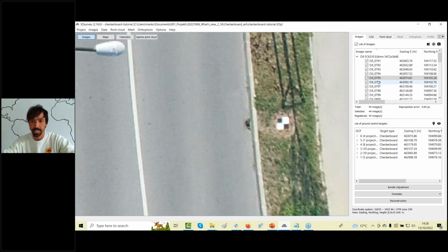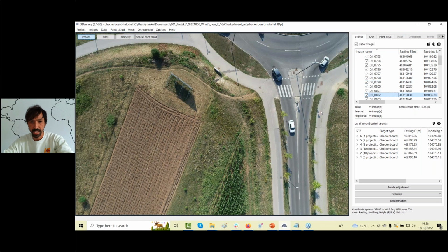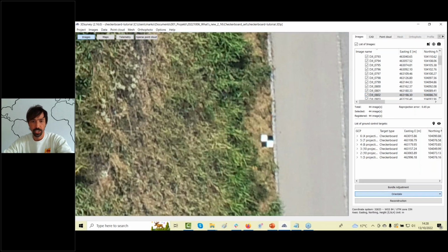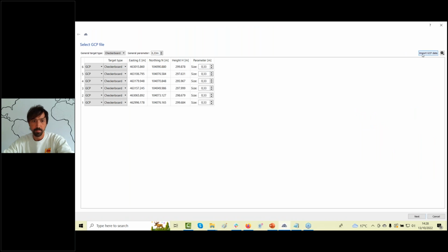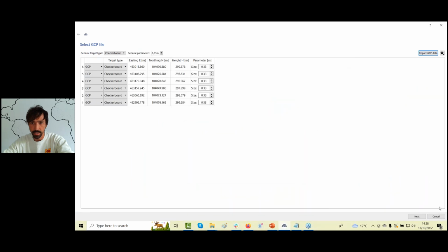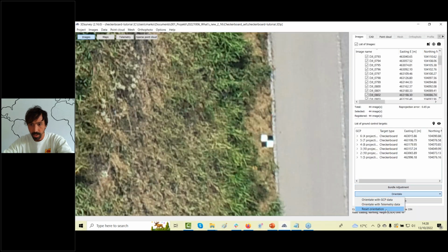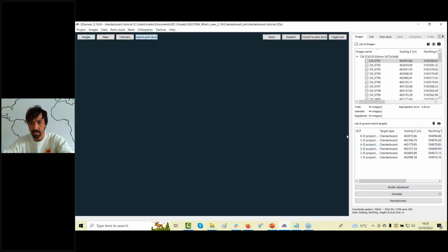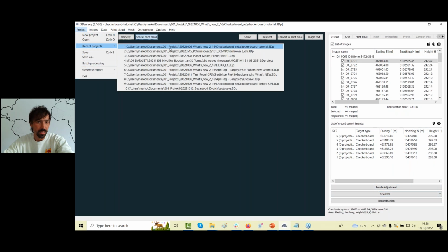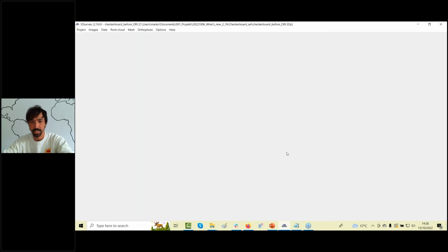And the workflow is actually pretty much the same as with the 3D survey target. So we placed, I think, 8 targets on this area. Here is another one. And if I go to orientate with GCP and import those targets. Let me first reset orientation. And actually I need to check a board before already. Okay, so this is the right project because this one is already orientated.